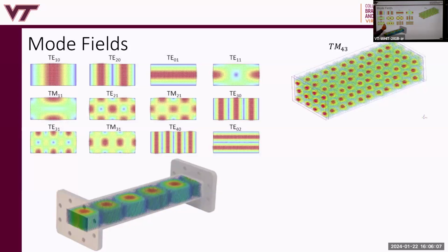Okay, you can do the same thing in the y direction. We have TE01 and we have TE02 here, and then we might have TE03, we do not. And you can vary both of them, right? You get TM11, 21, and so forth, right? TE and TM, and you can have higher order modes here where you have a very high frequency. Okay, good.